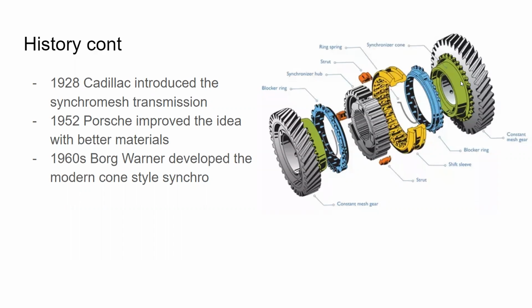So when you're selecting the gear, the sleeve will slide back and forth on this hub, and it will catch. You can see on this gear, it's got these little really small teeth on it. So when this sleeve were to slide back, it would catch on this and engage, locking that together. It would lock this gear with this sleeve to this hub, and it would transfer the torque through all of that into these splines to directly control the rotation of that shaft. So when you're shifting a transmission now, if you're grinding the gears, you're really not grinding the gears anymore. You're grinding the sleeve against these little teeth right here. That's what's being ground up.